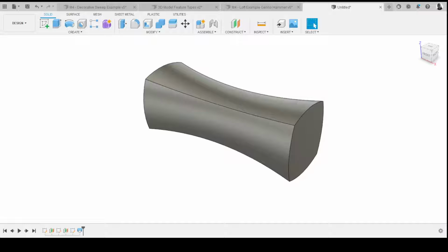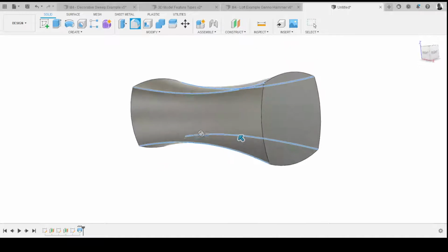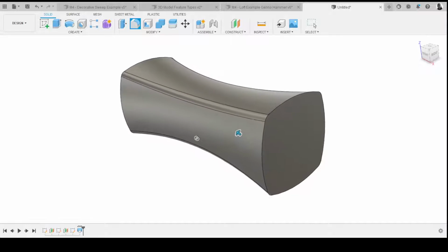So the last thing I did on this hammerhead was, at this point, just fillet it a little bit. So I'm going to pop some fillets, go to the fillet tool in the modify menu. Just a little aside about filleting. I'm going to put a 5mm fillet here. In terms of efficient filleting, it's good to always try and work towards clicking as few times as possible.